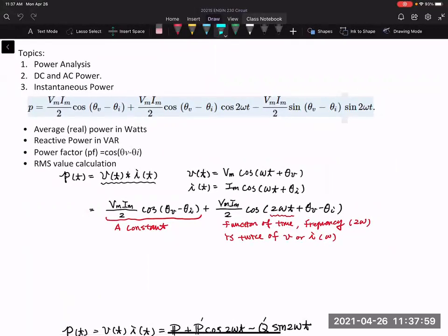Okay. So we started to talk about chapter 10 in the lab. And chapter 10 is about power. Now, for the AC circuit, how do you find the power? Because the current and voltage keep on changing. If you talk about power, that power probably is what we call the instantaneous power. It's the power at that moment in time, and you take the measurements of the voltage and also the current, you multiply them together, you get the power, which is instantaneous power.